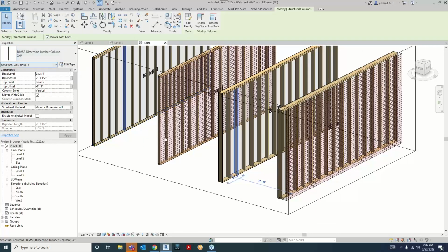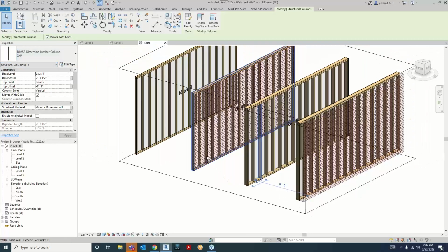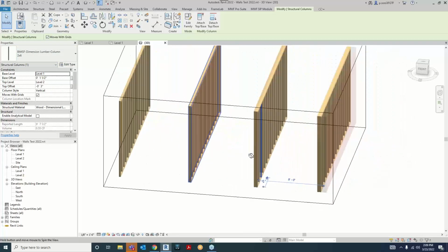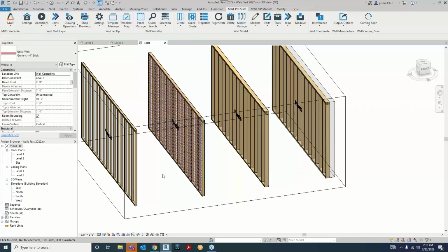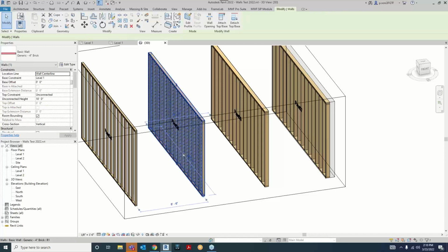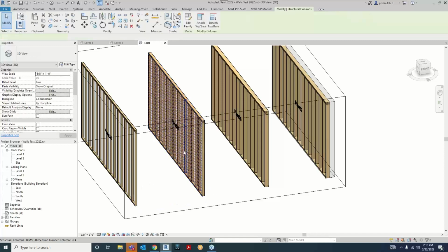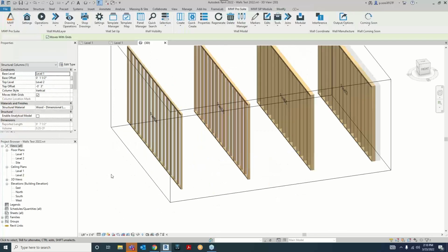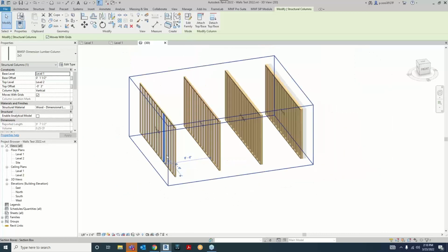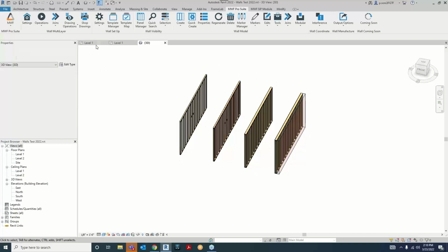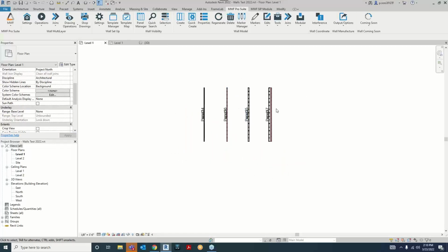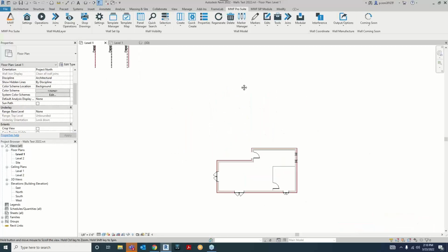As you can see, for the 6-inch wall, we assigned it for 2x6s. For our 4-inch brick wall, if I can select the member real quick. Oh, it's just not letting me. There you go. It's 2x4. And for our interior wall, 2x3s, as you can see, it's pretty simple. So that's how you can use the quick create tool in your project.